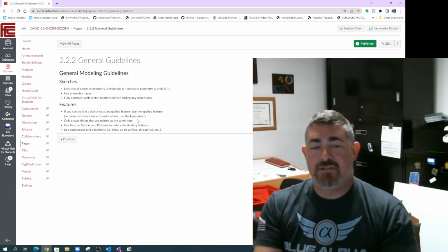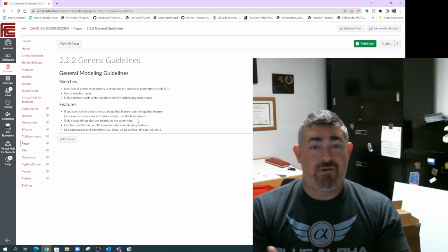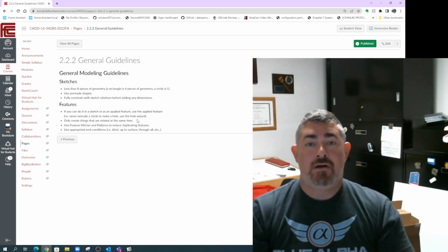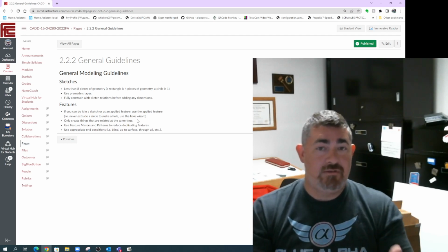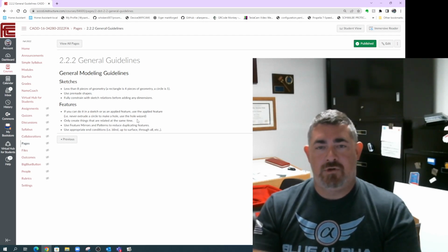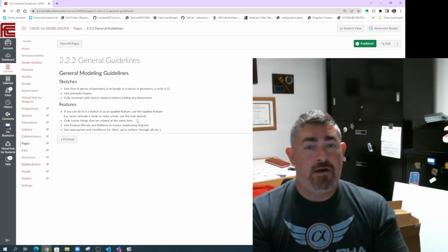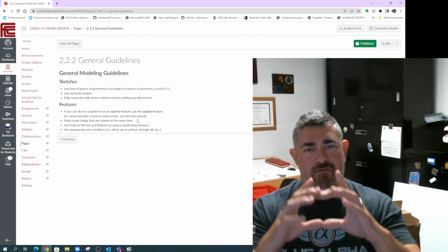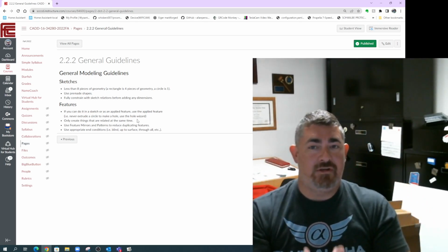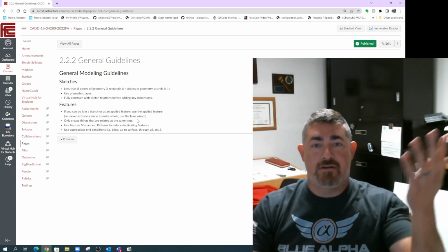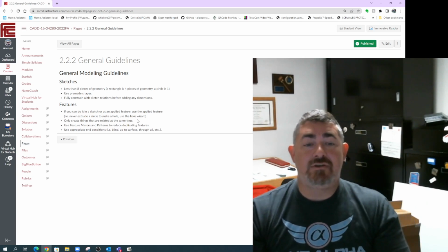Only create things that are related at the same time. Some of the programs like it better if you only create one closed profile. If you have two, sometimes they don't want to work as easy. Some programs work a little easier that way. So kind of a goal is to have one closed profile only, so that way it knows this is what I'm working on. SolidWorks will also let you do kind of an open line, and it'll let you pick which side to cut. But if you can close it out, that makes it easier. It doesn't have to guess what you're doing.